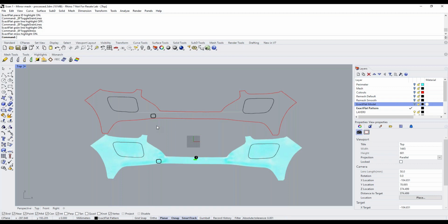As we mentioned, one of the big 5 best practices is scanning technique, where you orbit the scan surface approximately 30 centimeters away. You'll keep the scanner in constant motion, and with that constant motion, you will not overscan or underscan. You'll be sensitive to areas where there are, say, pits or ridges, or areas where the bumper meets up with the quarter panel, for example, where there's a slight gap between surfaces. And you'll get better at it.